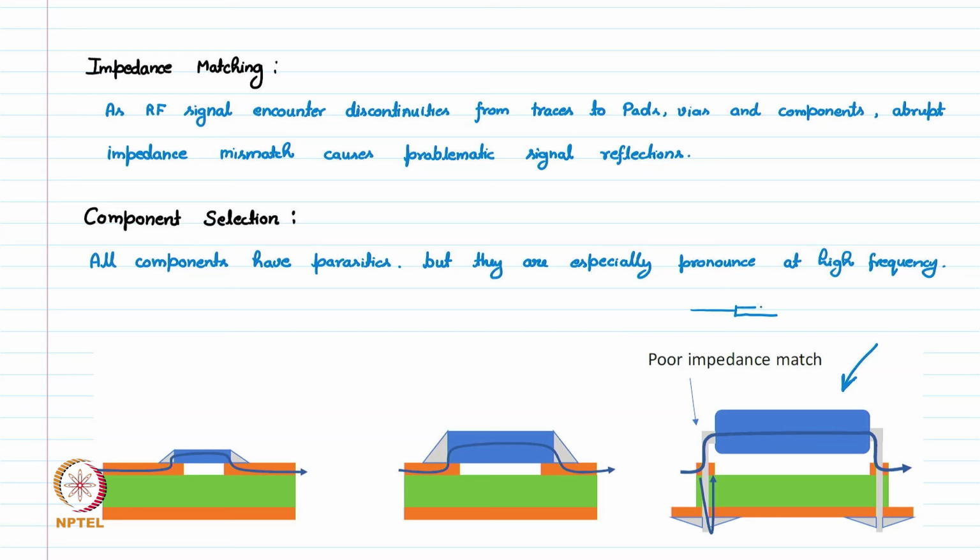We have this resistance, and these are two lead connecting wires which come out of it. We drill the hole in the PCB or this substrate. So this is your substrate. In this we drill the hole and bend these wires into this, solder it on the back side here. This is how we connect this 100 ohm resistance. So this is our 100 ohm resistance.